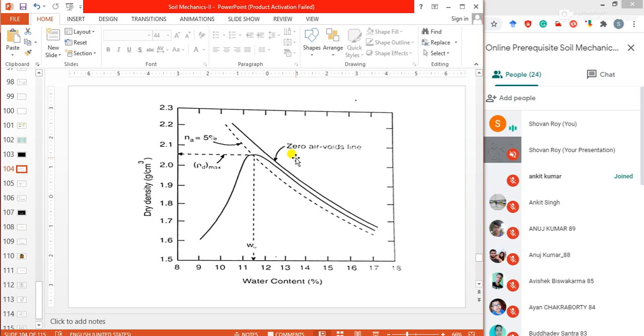When only a relatively small amount of water is present in soil, it is firmly held by the electrical forces at the surface of soil particles with a high concentration of electrolyte, which prevents the diffuse double layer surrounding the particles from developing fully. This is the physics.